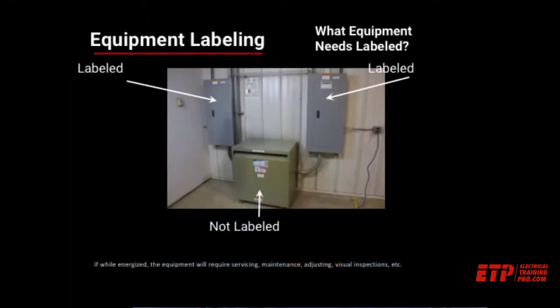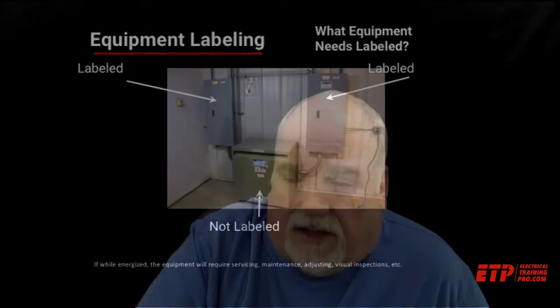What about in this photograph, circuit breaker panelboards? Yeah, those need labels because we're going to open those and verify the energization. Those are things we open up while energized sometimes. What about that transformer on the floor? No, we don't open those up to work on those. It's important that the equipment that while energized is going to be serviced or maintained gets a label. Raceways, conduits, pull boxes, those kinds of things don't. They won't need a label because we don't open those while they're energized. If we do, there are insulated conductors in there. So things that while energized require service, maintenance, inspection need to have a label.